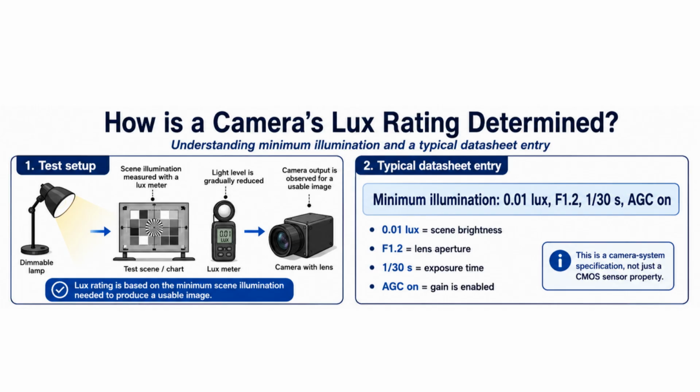A camera's lux rating is determined through a controlled, low-light test. First, a dimmable light source illuminates a test chart. A lux meter measures the amount of light falling on the scene while the camera observes the same target. The light level is then gradually reduced until the camera reaches the minimum level at which it can still produce a usable image. The result may appear in the datasheet as 0.01 lux f1.2, 1/32nd AGC on.